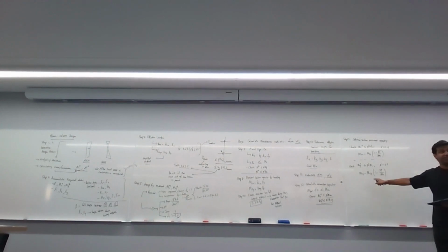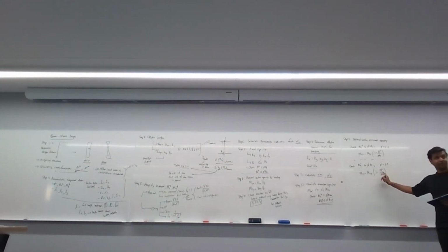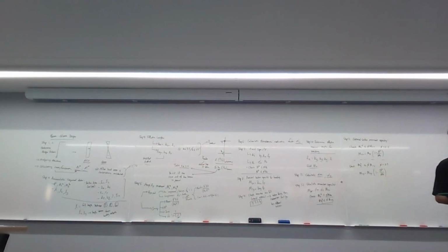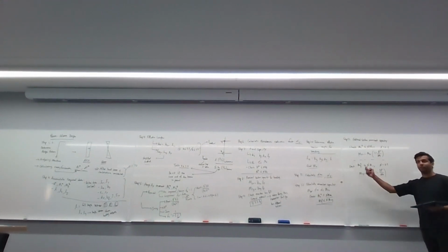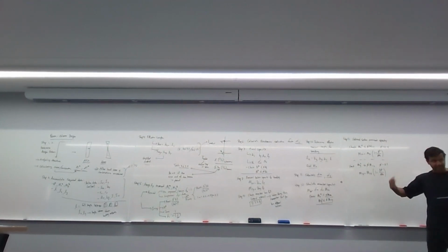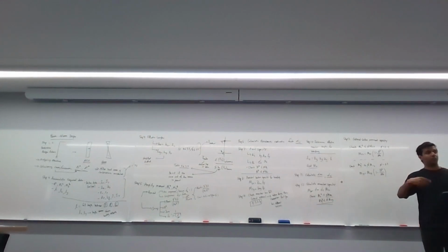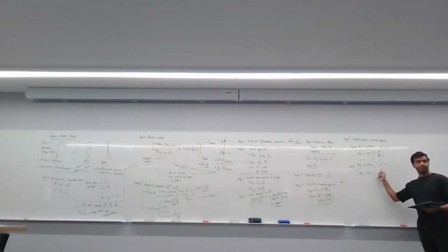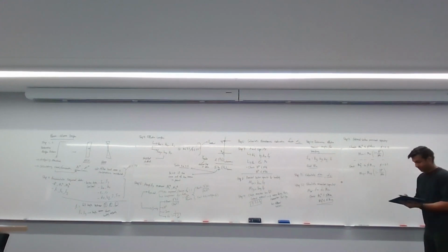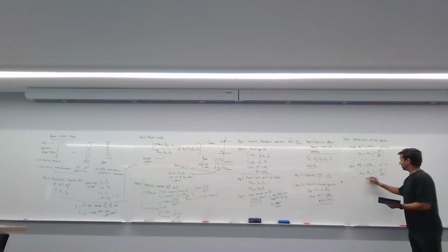Okay, remember, these values depend on N star. So remember, in step 1, when we are collating which N star and M star we're going to use, if there are two N stars we're going to use, one from combination A and the other from combination B, then this will yield two different values, right? So for combination A, Mry is going to be this. For combination B, Mry is going to be this. You need to remember, Mry is a capacity value, yes, but it's not just dependent on what it is. It's dependent on how much load you're putting on it. Mry changes based on how much load is applied. Okay, you've got to keep this in mind. All right, that's step 13.